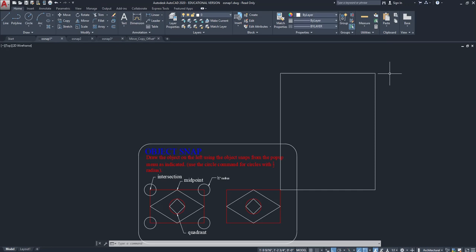I think one of the most tricky points about AutoCAD is that, right now as we're looking at this, other than I just drew something here, I have no indication of how big these things are, right? I can look at it and say that this rectangle right here is 400 feet by 400 feet, or I could look at it and say it's 1 inch by 1 inch. I have no kind of graphic illustration of how big these objects are, right? So I need to be able to measure things. I need to be able to draw things and then measure them in AutoCAD, okay?